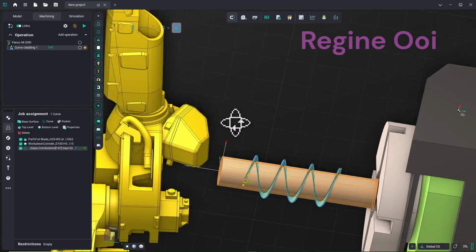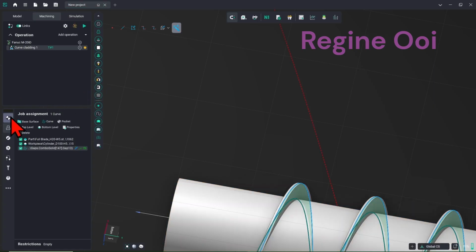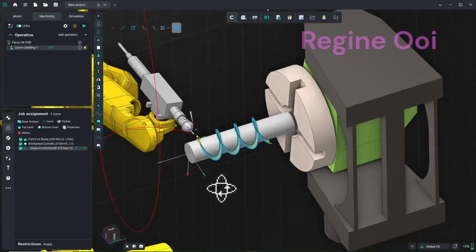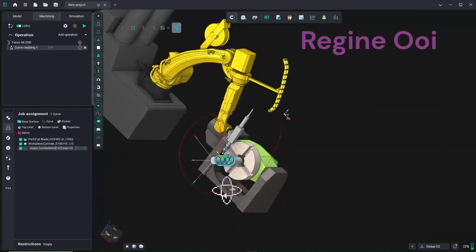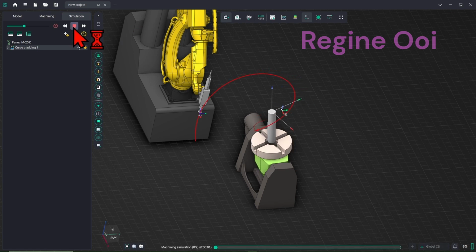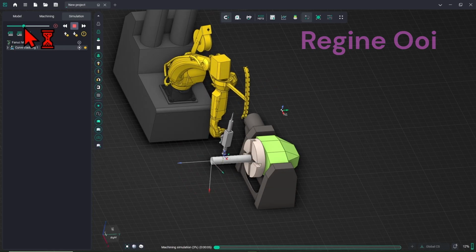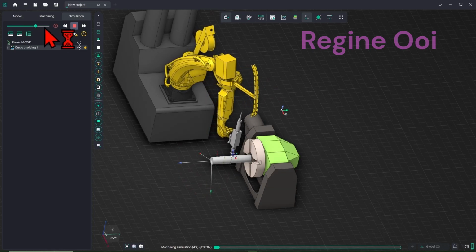Now, we adjust the start point by clicking on this: Machining side and inverse curve. After adjusting, execute the operation. Switch to Simulation tab. Reset to clear previous simulation record. Click Run to see the result. Now the tool path starts from the front side.